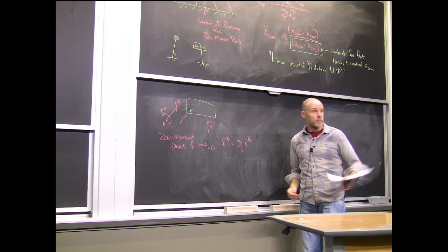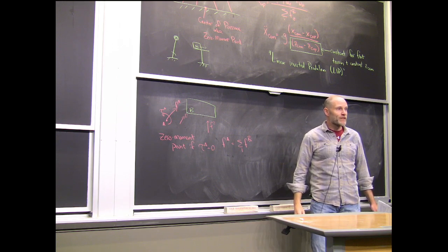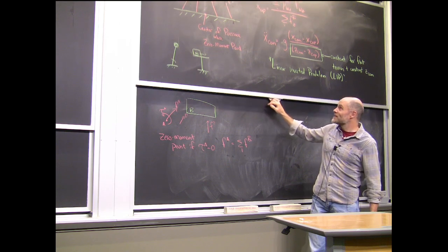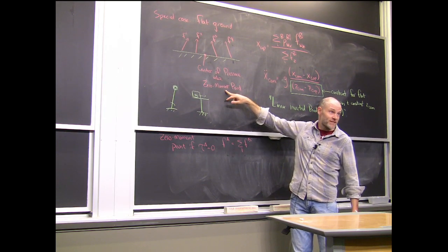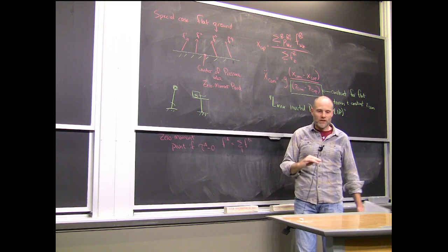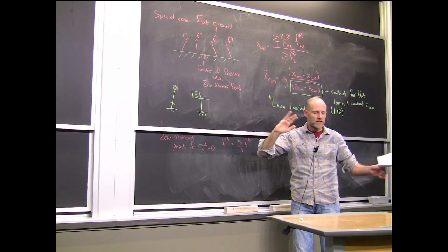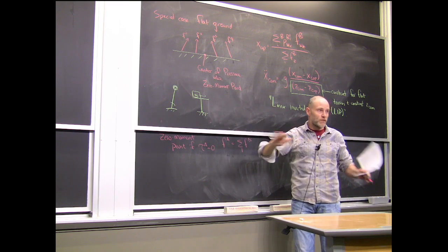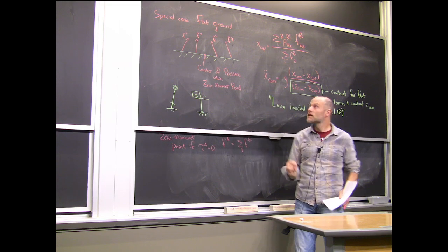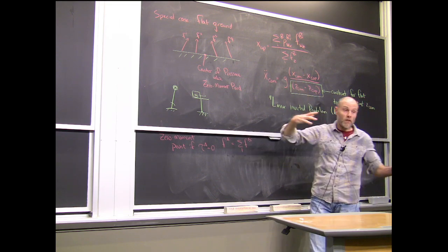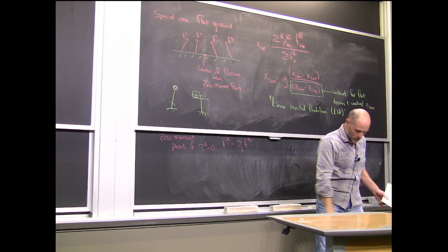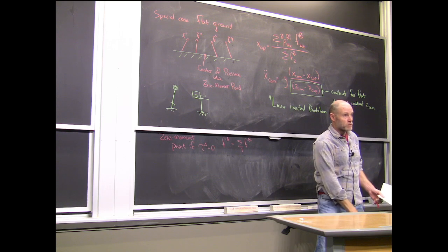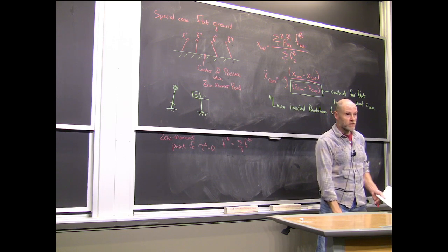Yeah, can the zero moment point be outside the area of support for a foot, or does it have to be within the foot area? Awesome question. That's the place where these definitions can depart. Let me make sure I answer it carefully. Certainly the center of pressure can never leave the foot, as I've defined it. It's just a weighted average of the support polygon, okay? So if I put a convex hull around all of my contact points, if I'm on flat ground, then the center of pressure will always be somewhere in the convex hull of my contact points.